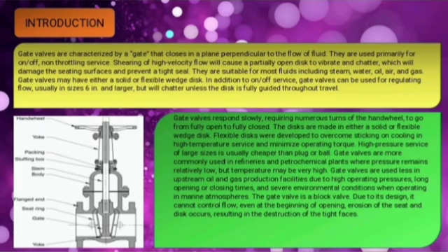The gate valve is a block valve. Due to its design, it cannot control flow. Even at the beginning of opening, erosion of the seat and disc occurs, resulting in the destruction of the tight face.